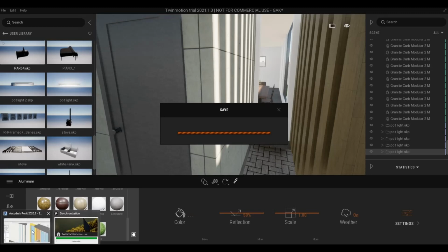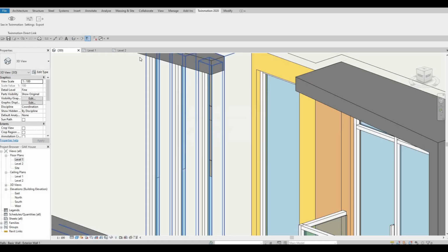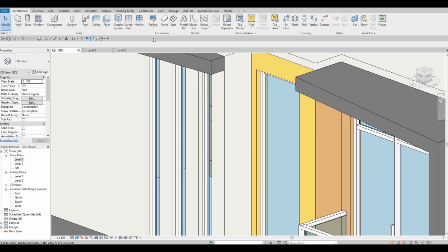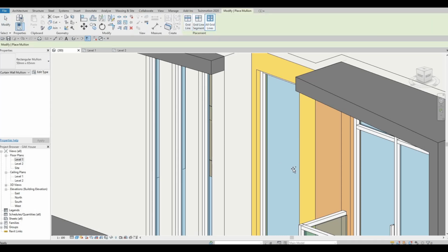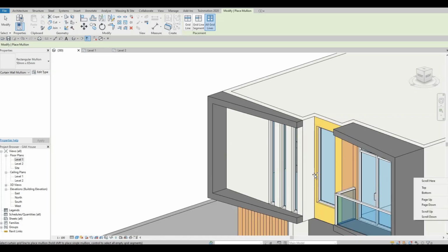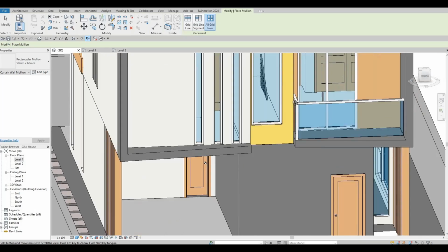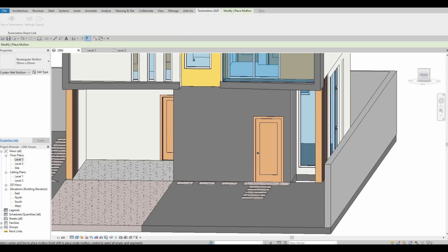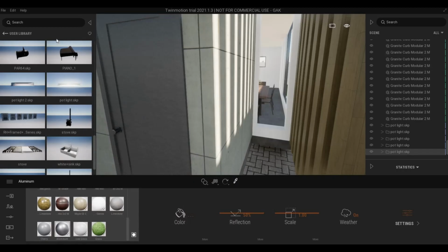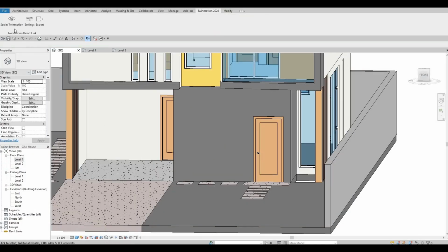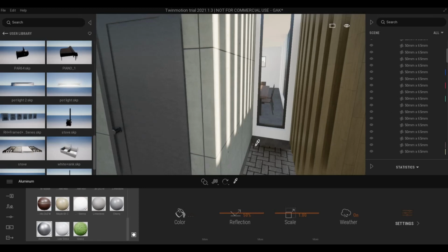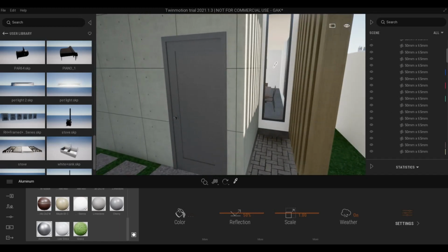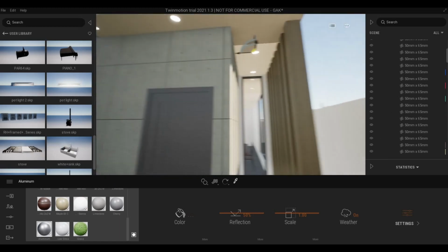So we just need to go back to Revit, and then click architecture, mullion, all lines, all grid lines, and then after that zoom out or rotate, and then we could add it here. And then after that, make sure that the saving part is done. So that's done. Now we could send it, and as you can see, it recognizes it.